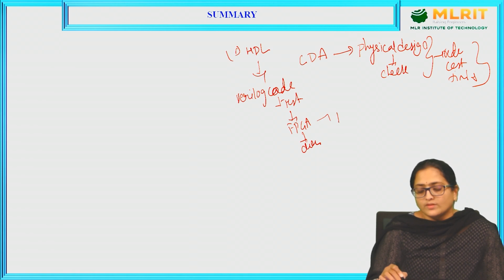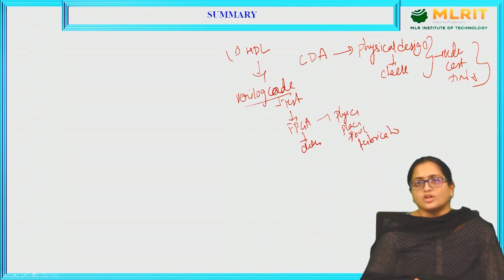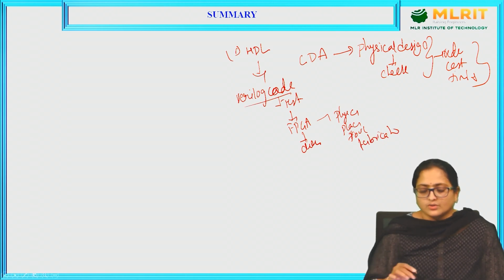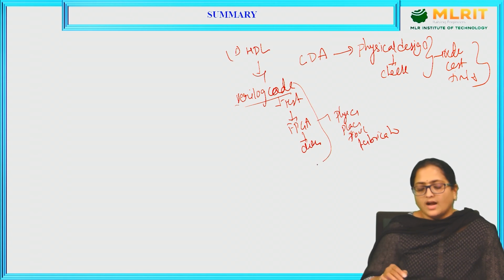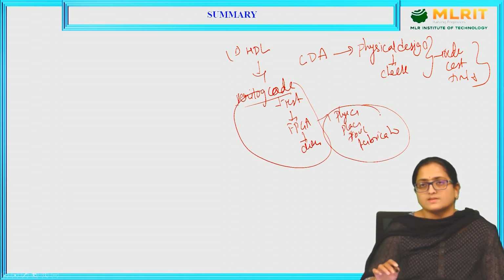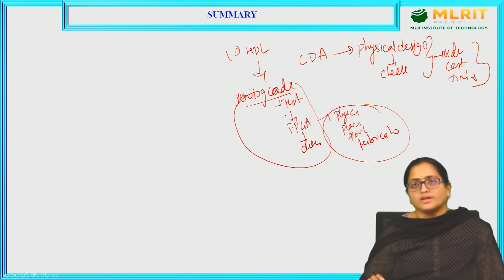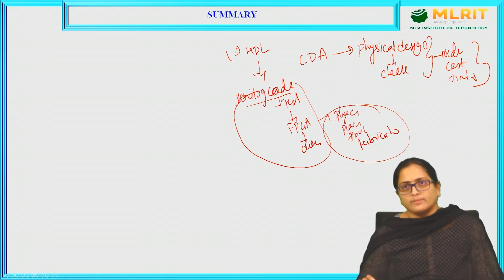Then you can go with the physical layout like placement, routing, fabrication, everything can be done after checking the Verilog code. If you have any errors here, you can check the Verilog code again until you get the correct output. Then you can go with the placements. So, the cost and timing factor is reduced here by doing HDL code, placements, routing and fabrication.